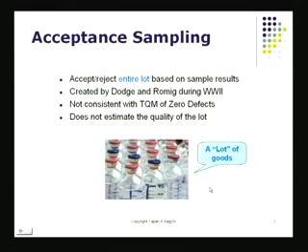Now, if some particular bottle turns out to be containing less liquid, the process of filling the liquid in these bottles is going to be a defective one, and the lot itself also will be a defective lot. So in fact, what we will be trying to do is, we have this large lot that has been supplied to us, and instead of inspecting each and every bottle that is here, we'll probably take a few samples out of this, and on the basis of inspecting the quantity of liquid in those bottles, within the sample, we'll decide whether to accept the lot or to reject it.